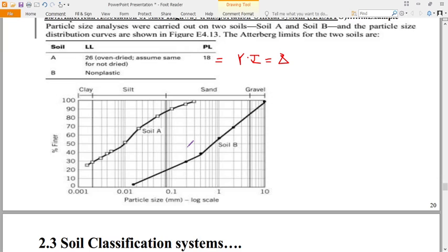The second step is now to name the material. Step 2. So we can get our percentages from other sieves. Remember, you have sieve number 10, sieve number 40, and sieve number 200. For material A, we have already said it's a fine-grained material. Our purpose now should be material B, which is a coarse-grained material, to meet all these three conditions of the sieves.